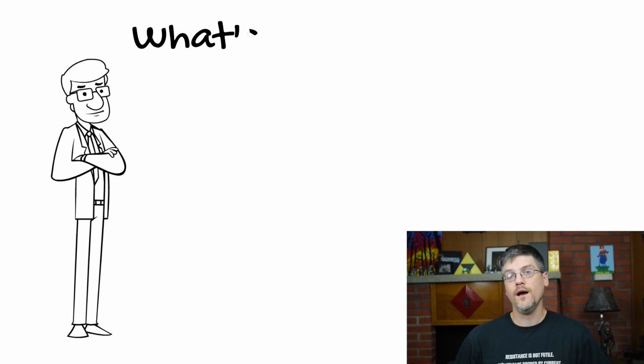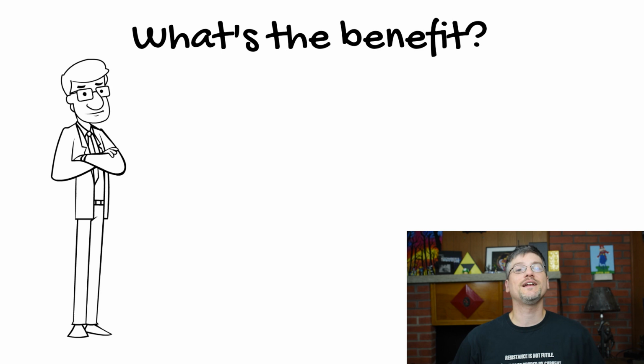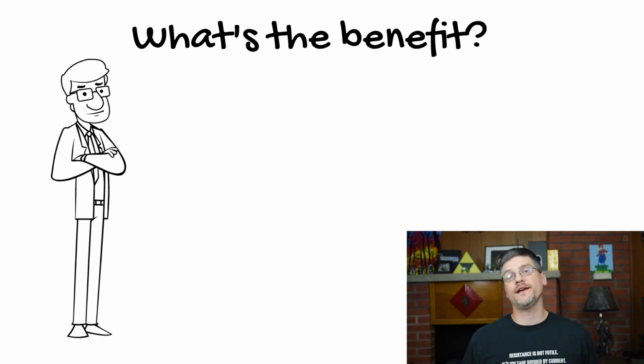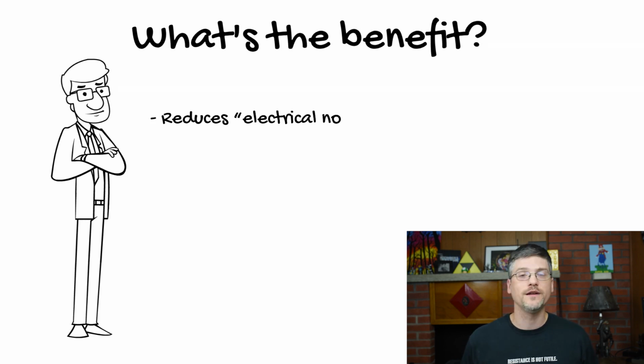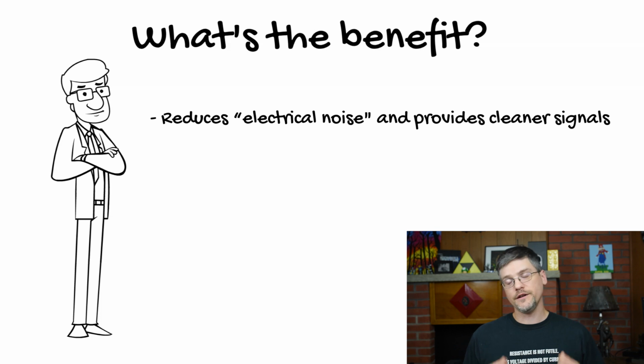Okay, this all sounds pretty easy, but what's the benefit? I'm glad you asked. There are plenty of benefits to having a properly designed ground plane. Gone are the days of 56K modems, and now we're rocking megahertz or even gigahertz speeds in our signal processing. A cleaner path to ground reduces electrical noise, which is especially important for RF circuitry, because any incoming or outgoing signals need to be as pure as possible, which helps facilitate cleaner signals for the receiver and the transmitter.